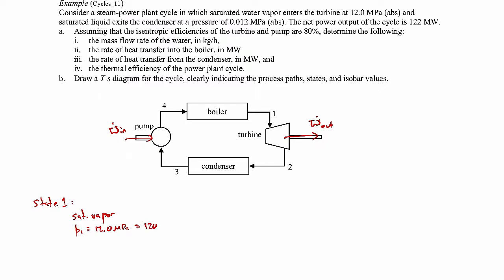That's equivalent to 120 bar. So we can go to the saturated property tables for water and look up the corresponding temperature for that. That'll be 324.68 degrees Celsius.